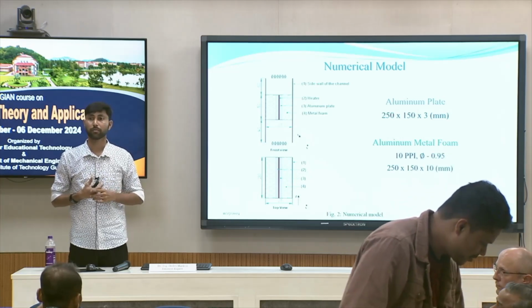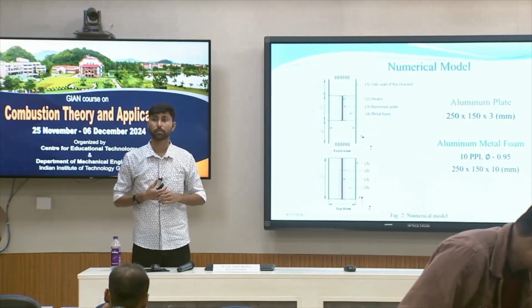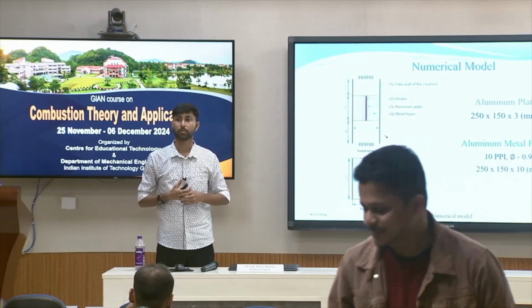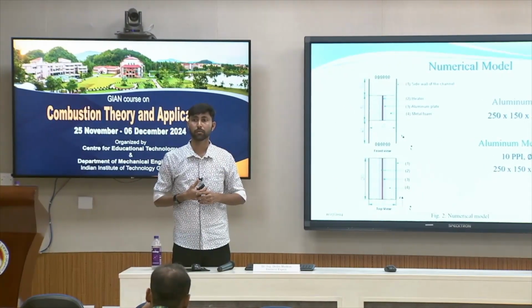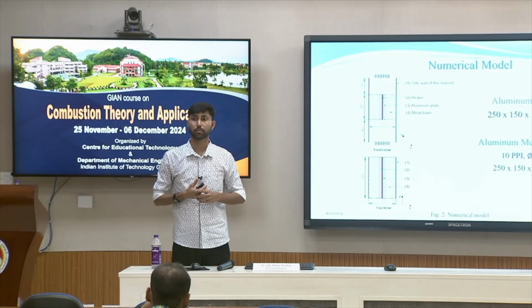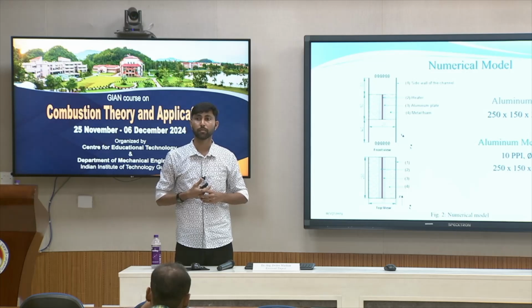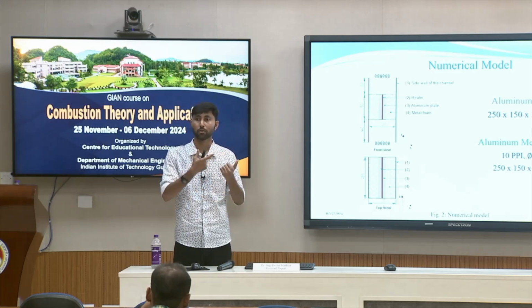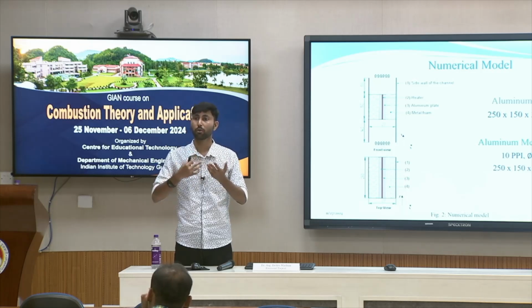Another point is that whenever you simulate with a smaller diameter or a larger diameter, the surface area getting attached to the heater will vary. So the conduction of heat towards that foam will vary. Definitely, that is what I told you. The factors of pore density and porosity play a major role in heat transfer enhancement, so by varying those also, we can do the investigation.